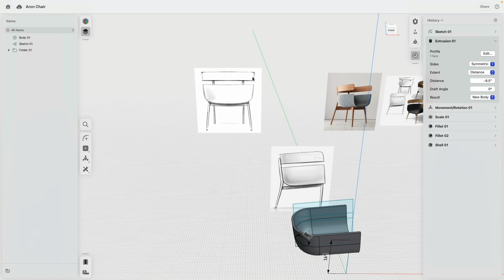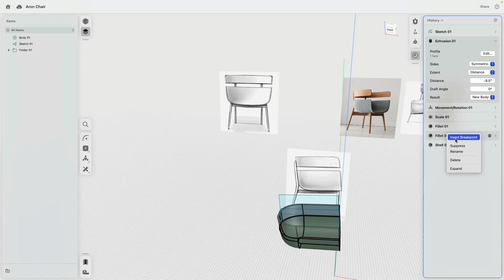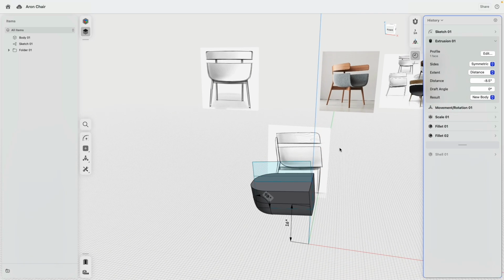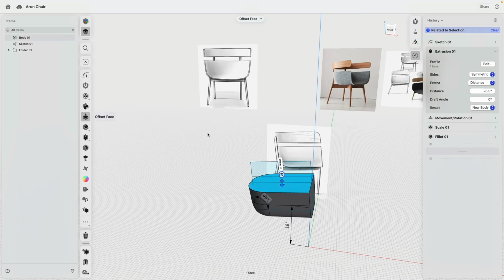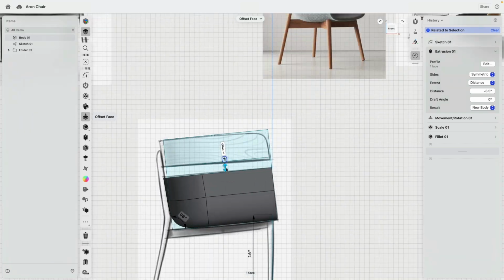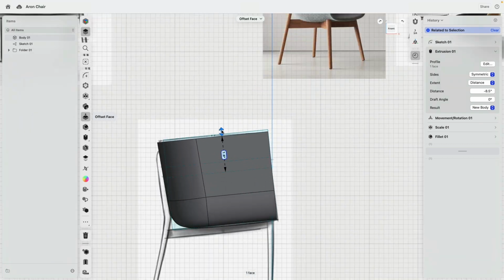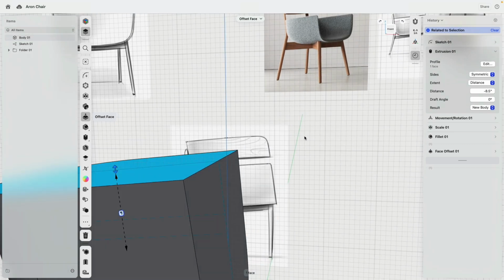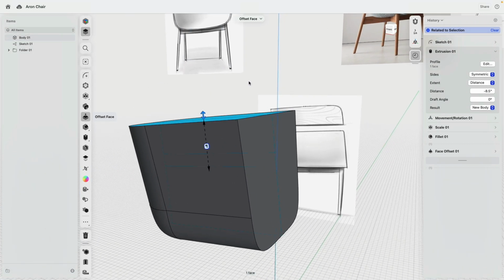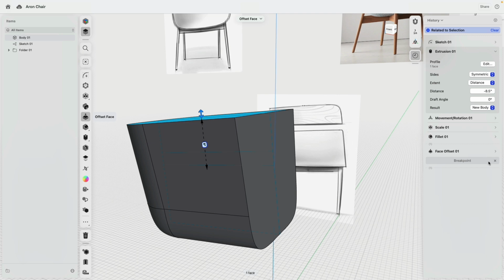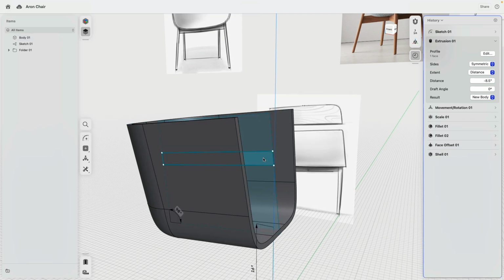We can also see that the wooden rim that goes around it is not a straight extrusion. So before we do the shell, we should go back to here. Because this one, how do we do this now? We extend this. Plop. There we are. Okay. And then we do the shell command, and this is all good.